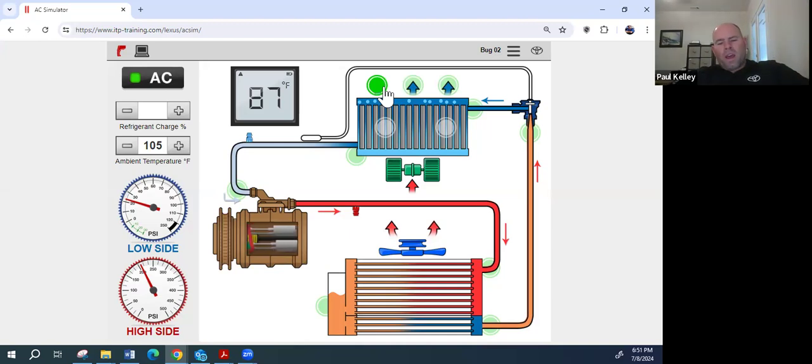Going back to week one, we no longer have all that latent heat being transferred into the refrigerant through the change of state. You remember that? When that refrigerant is evaporating, it's grabbing a bunch of heat. But you don't have a whole lot of refrigerant in there to really grab the heat because it's all evaporated up, and it starts to get warm. And just like that, boom.